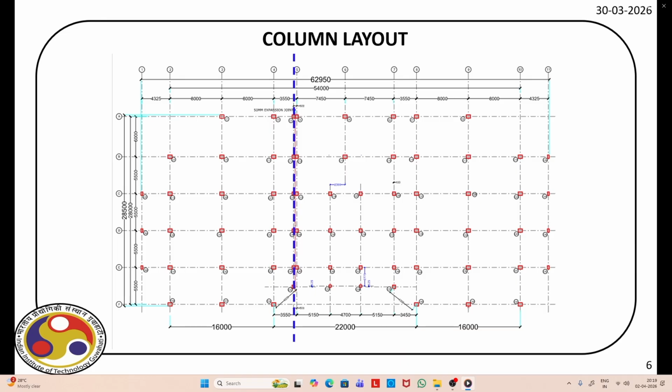So we'll construct the grid points. So the sequence of modeling will be first the locations of the columns that we'll make from the grid points. Then story by story we'll create first the columns and then we'll connect the columns using beam element, and that will form the beam. And that's how we will develop the model in the vertical directions.